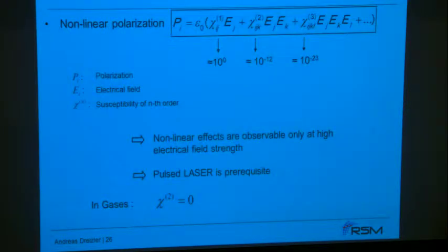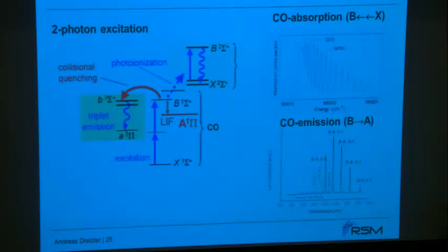And then you do a calibration. In the calibration, you do that in heated flows and as well in a laminar flame, where you know exactly the CO concentrations from 1D simulations. I shouldn't say exactly, where you have a good estimate of the CO concentrations. And you do that calibration in dependency of the temperature.